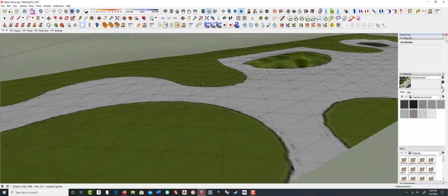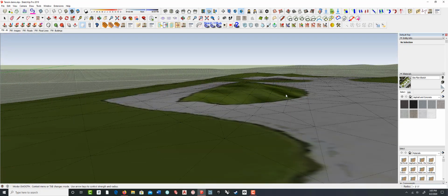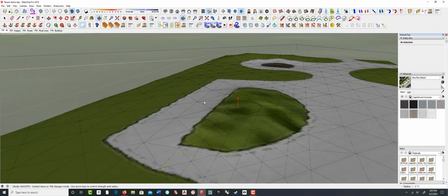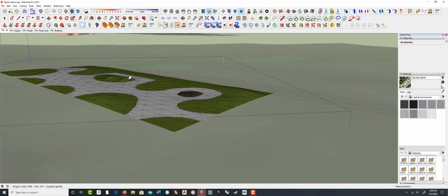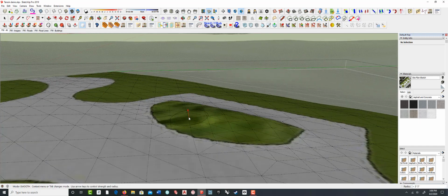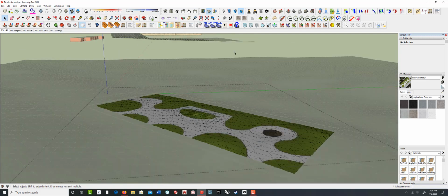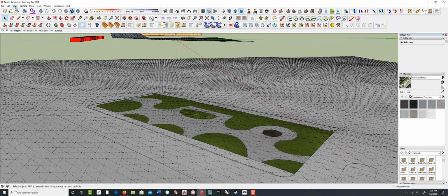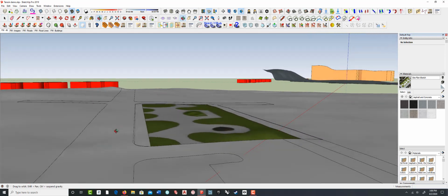So this gives you a really quick, fluid way to make those kind of landform adjustments and changes by using the image as a guide, as opposed to having geometry that's breaking this into pieces. And again, I'm not worried about this because I'm going to have a stage sitting there. Okay, so that's a real quick introduction. Again, I'm not going to go through all the features of Artisan, but it's a great plugin. It's super for doing grading, and it gives you a really quick way to go in and make those changes.